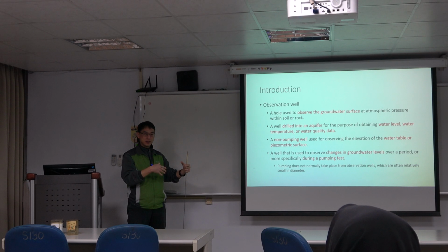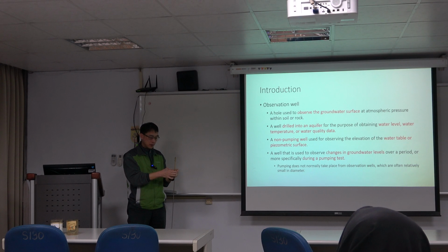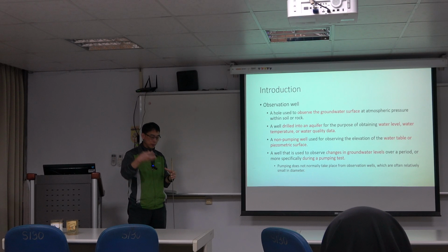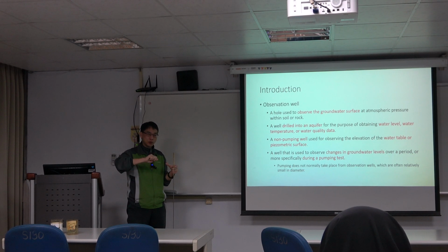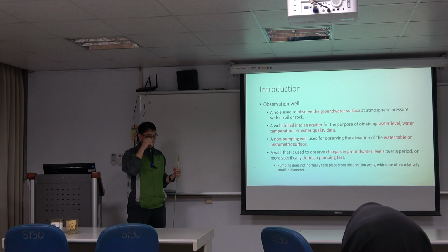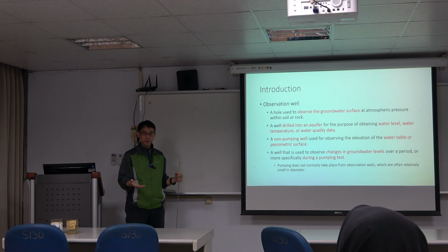So their problem is that they tried using 2-inch wells and put the pump inside, and they ran at maximum power, but the water level still stayed constant because the material is gravel. I said that they are very close to the river bank, so it is mainly gravel, a highly permeable material.